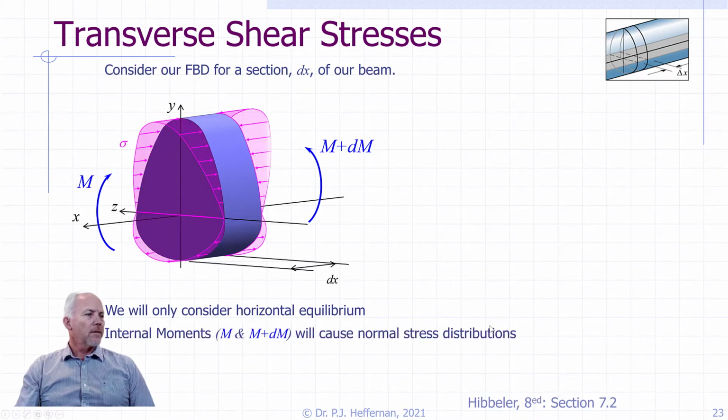What we want to do is then reflect those in their stress distribution. So remember everything we've learned about our normal stress distributions. We have our neutral surface, and we put sigmas on it. You're going to have sigma on the left side, and sigma prime on the right-hand side, which should be higher than sigma, because M plus dM is implied as larger than M.